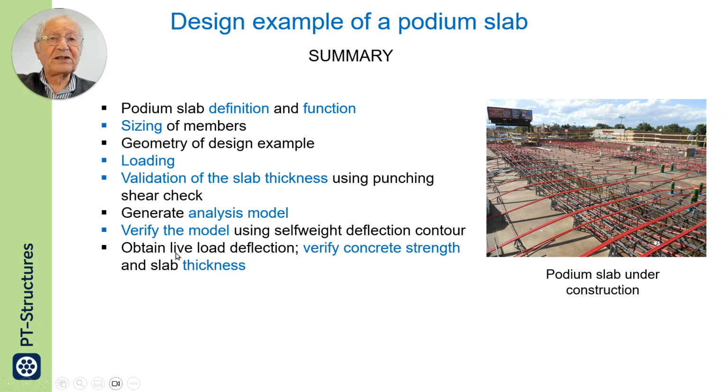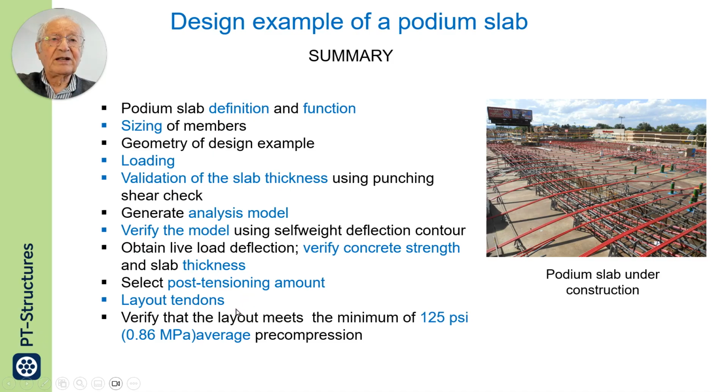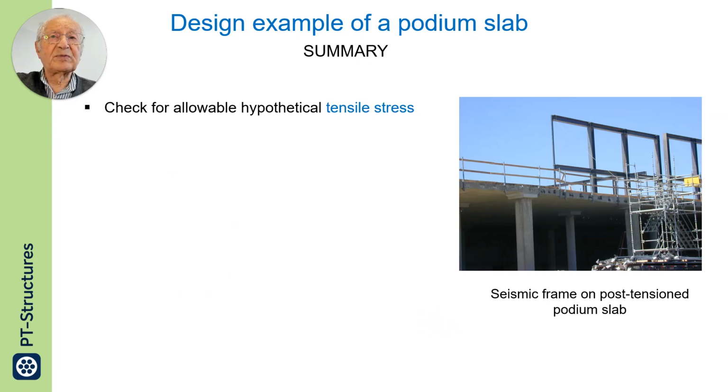Then we obtained a live load deflection to verify the strength of the member and slab thickness. We selected post-tensioning and the layout of post-tensioning. We verified the minimum 125 psi by assumption of pre-compression. We obtained solutions for serviceability.